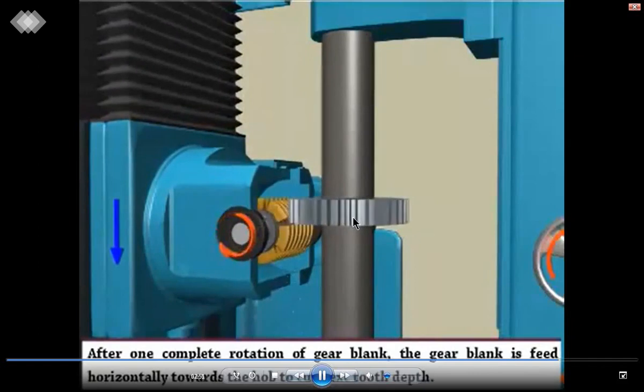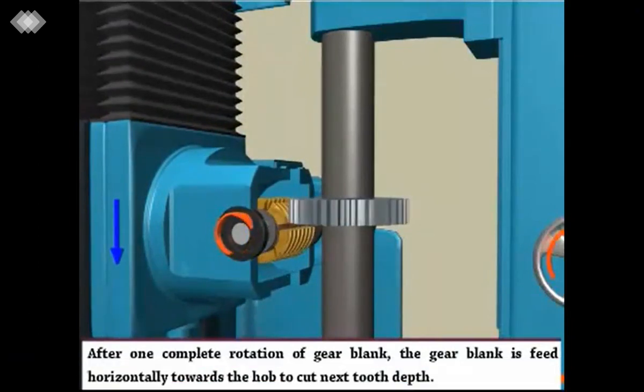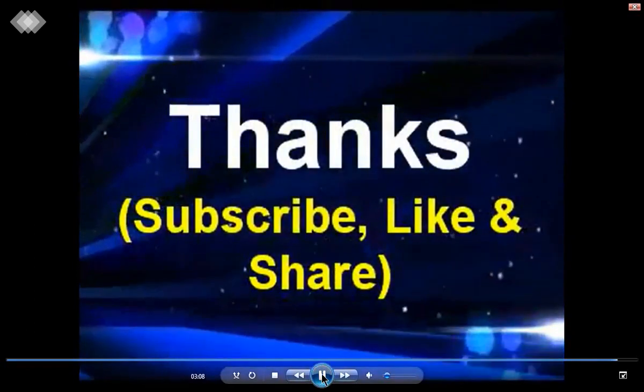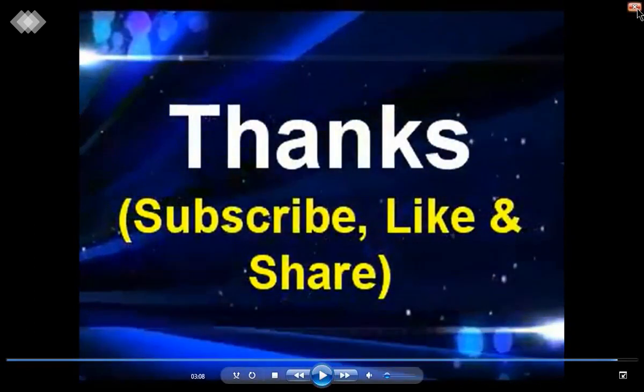The gear blank, or the gear workpiece, is also rotating. After one complete rotation of the gear blank, the gear blank is fed horizontally towards the gear cutter, or the hob. This process is repeated until the required depth is obtained. So this is the animation of the gear cutting process.